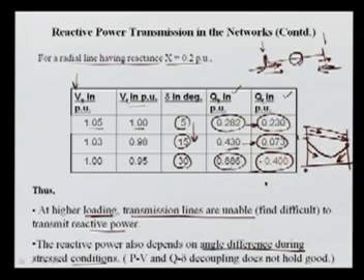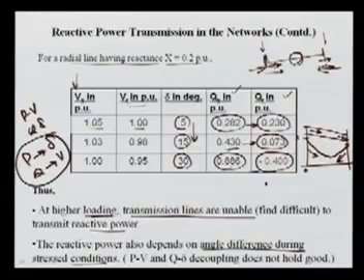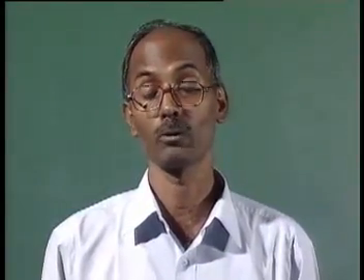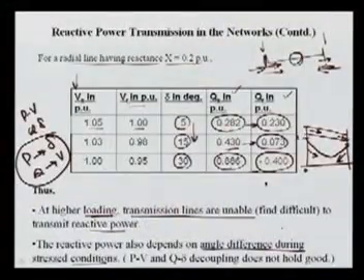Normally, you know that in load flow, we take this P-delta and Q-V decoupling. This means we assume P is coupled with delta and Q is coupled with V, and based on that we normally go for decoupled load flow or fast decoupled load flow analysis. We are taking the solution. But in stress cases, it is not possible; we cannot take this decoupling, and then we have to go for the intact system and without considering the decoupling as well.